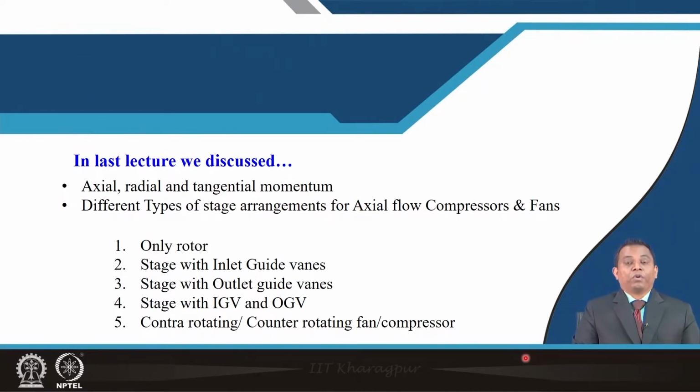What all configurations we have discussed: only rotor configuration, and stage with inlet guide vanes. So we will have inlet guide vanes that will be followed by rotor. We have stage with outlet guide vanes, meaning rotor will be followed by the stator. We have inlet guide vane as well as outlet guide vane, and we have discussed important aspects of the contra rotating or counter rotating fan or compressor configuration.